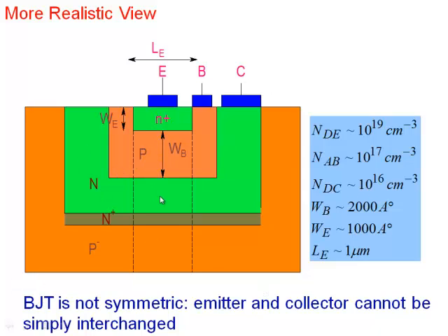So once the electrons come here, they go to the N plus here, and then they travel along the N plus layer laterally, and then they go to the collector here. So it's all done to minimize some series resistance, collector resistance of the transistor here. Okay, so that's a better cross section of a bipolar junction transistor.